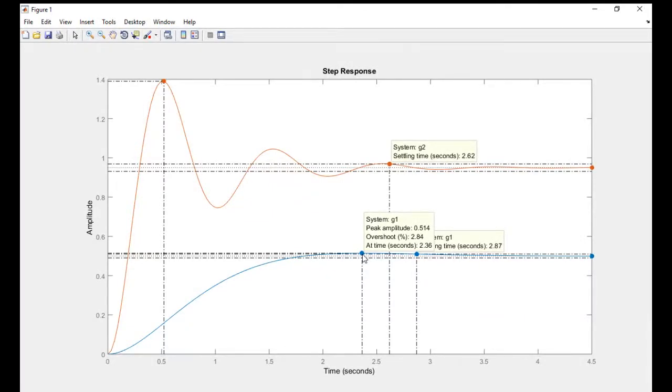All right, let me just correct myself for a while. What we're looking at is not the disturbance plot, but the one that we did earlier for the steady state error due to the unit input. Remember that unit gain feedback system? It's the same system, but what we're looking at right now is the steady state error due to a step input for k equal 1 and k equal 19.